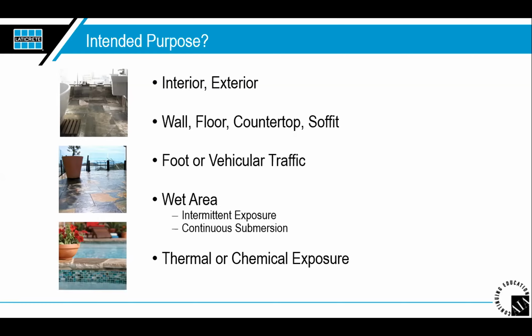Malls are a big deal as well. I've been a part of projects where we went into mall scenarios, for example, and we consider that to be just a heavy foot traffic area. But indeed, whenever the malls are changing out the stores, the storefronts, they're bringing in steel-wheeled rollers. When they have to change out the lights, they're bringing in steel-wheel rollers, and that does cause an issue if you don't have the proper coverage and proper installation materials for the tile installation that was there.